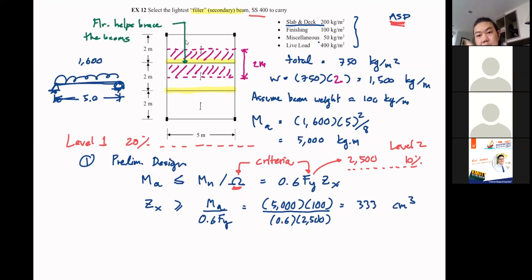Like a truss, I'm telling you, you don't have to consider the weight of the truss members in your project because it's going to be very light. But let's say in the future you design a mega truss and you don't include the weight, that's going to be a problem. It's your judgment as well, because the weight is real, correct?